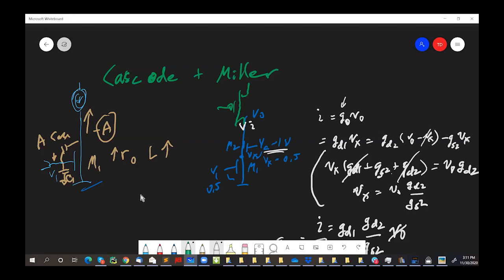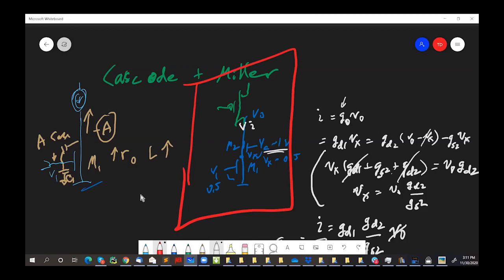I mean, when you go above threshold. In subthreshold, the transconductance only depends on the current. But you can afford to make them wide so that they stay in subthreshold longer, with bigger current. And so this is a nice sweet spot, right? This whole circuit here is just a really nice amplifier stage in subthreshold because of this combination of effects. We use it all over the place.